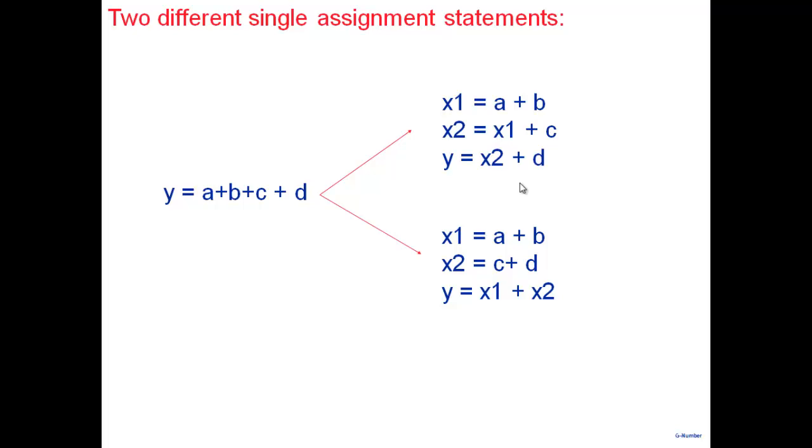What are the consequences? Consequences are always how much area my circuit will occupy, how much time it will take, what is the clock rate at which I can run, what will be the latency, what will be the throughput. And these divisions that you see here also have consequences for how much power eventually my system will take. So there are power issues also. Just like delay is there, we are not talking about power now. Power will come to us at the circuit level. But there are those issues here. So at each stage, you're taking a decision. Should I break it up like this, or should I break it up like this? Or there are other ways of breaking it up. Okay? And remember, the higher up in your design that you are, the more crucial the decisions are.